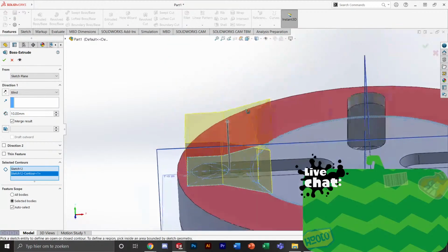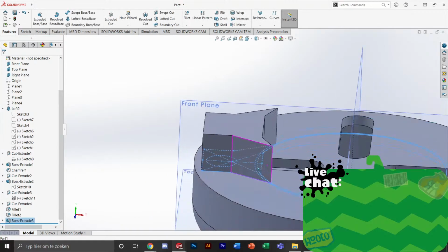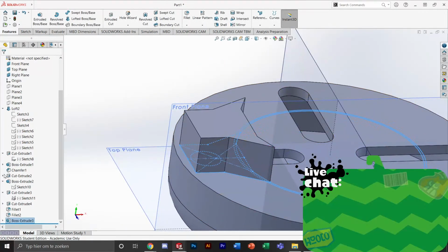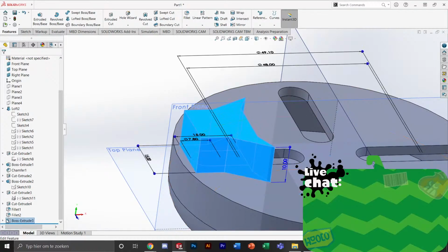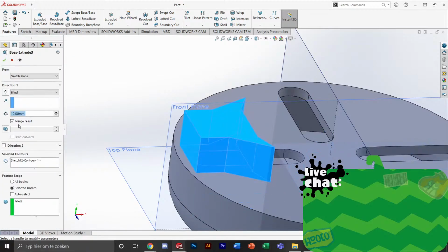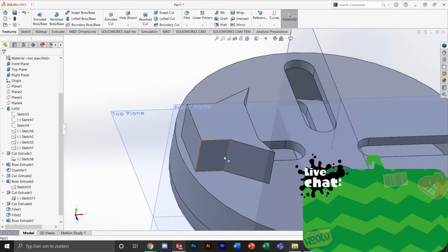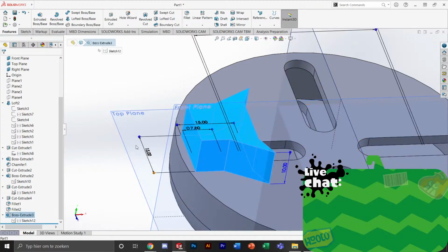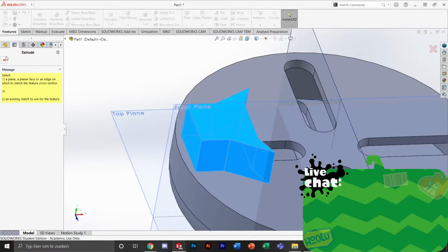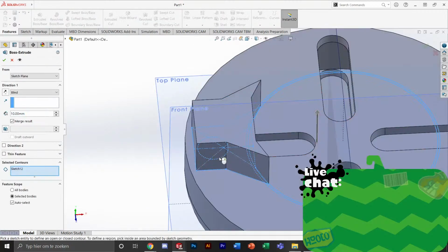Then I can follow this pattern and have a little claw come up. Oh, I forgot. Because this way it's just part of the handle, but we need it to be a separate moving piece. So, do not merge results. And now it's a separate piece. Then we can use the same sketch again. Select the sketch, use it again, but now to make the post.